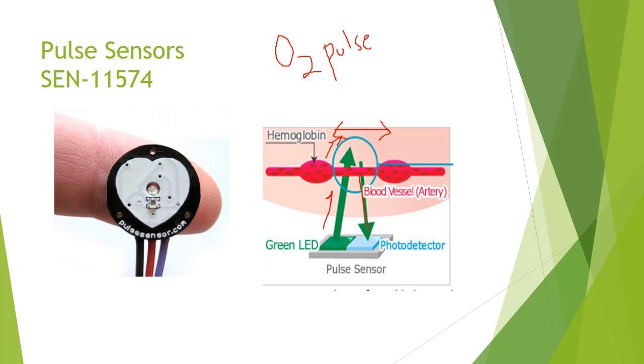Okay, so it keeps on sending the green lights, and between these two pulses the timer will detect the timings. Once it notes down the timings, they are converted into beats. It keeps on sending the green lights, and the photodiode or photo detector keeps on absorbing that light.